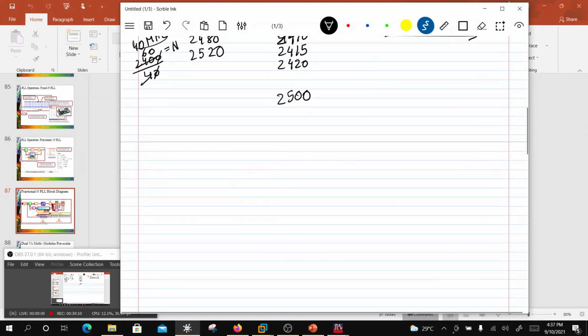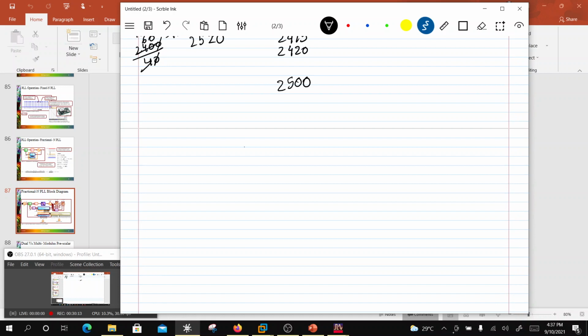Now to sum this up, let's say that there is a line following robot. This robot is checking at different steps over a period of time. You can say different steps in time, or different steps in length. So at this point it is making a comparison, at this point, at this point, and at this point. The robot is following this line and it is deviating, and at this point it says that the line is on the right hand side, so let me make a correction. So it made a correction, right?